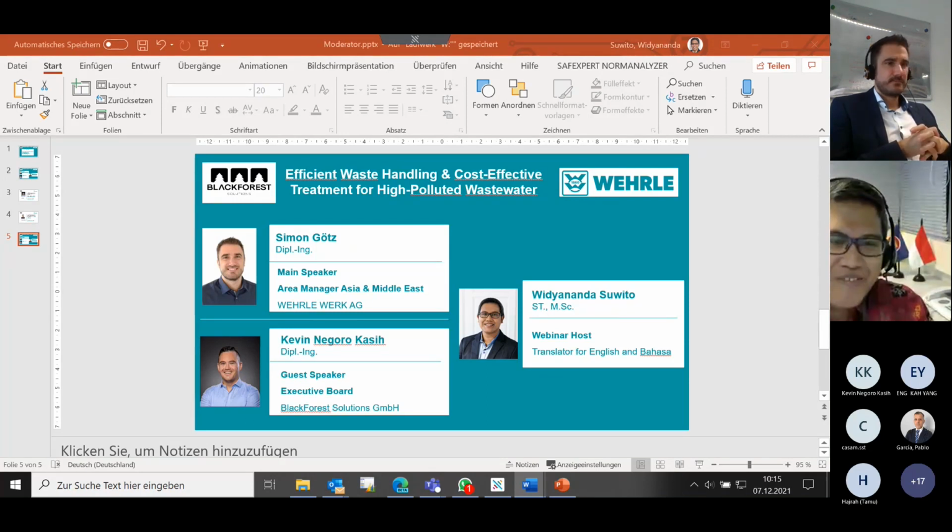We still have several questions, but this is the question from Mr. Karim. Why does WEHRLE use the injection of air instead of pure oxygen in its treatment plant? An MBBR plant, for example, normally needs pure oxygen injection, and it becomes a key parameter of the design and plant performance. But here in MBR, you explained that we just inject air instead of pure oxygen. Yes, clearly we never inject pure oxygen in our plants, since it's much more expensive.